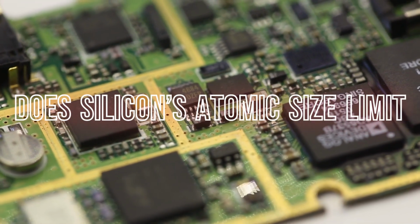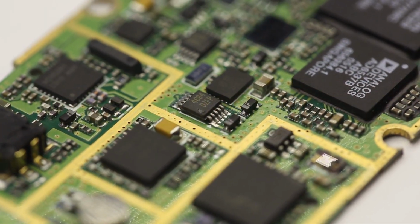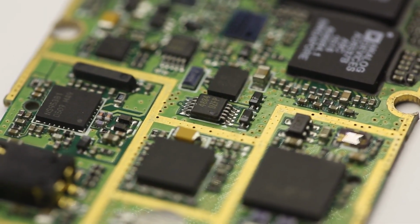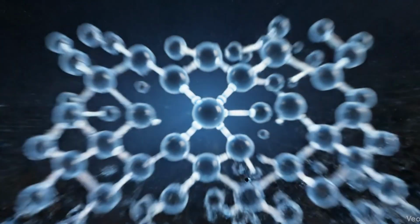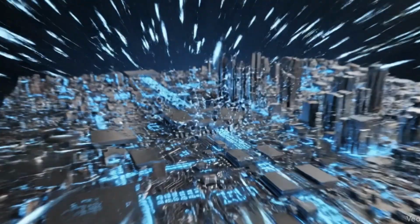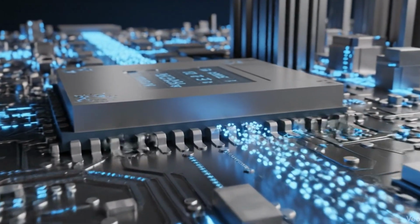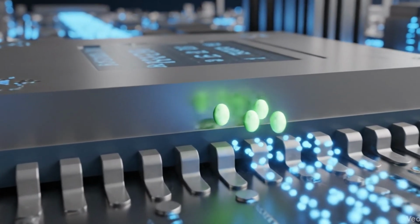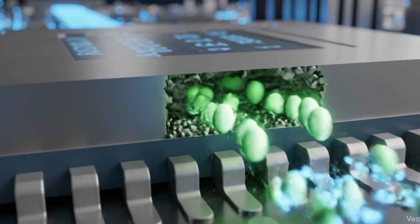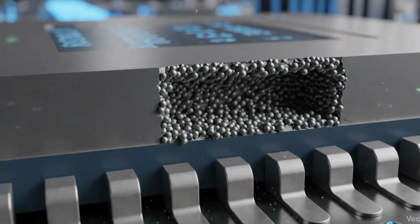Does silicon's atomic size limit how small we can make transistors? Silicon atoms have an approximate atomic radius of 111 picometers, or about 0.1 nanometer. But that doesn't mean we can build transistors at that scale. Today's 2 nanometer technology node already pushes silicon near its physical limits. Not because we are down to individual atoms, but because quantum effects like tunneling, leakage, and variability due to atomic scale fluctuations start dominating at these scales.